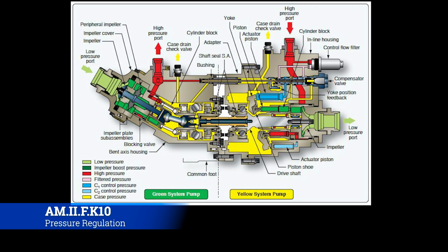Okay, so here's another device that you'll find inside of the hydraulic systems, which are actually pretty cool. It's called a power transfer unit. Now, this is out of an Airbus aircraft. Notice that you have green system pump, yellow system pumps. They divide their different hydraulic systems up in colors, as opposed to Boeing, which does hydraulic system one, or left and right, if I remember right.